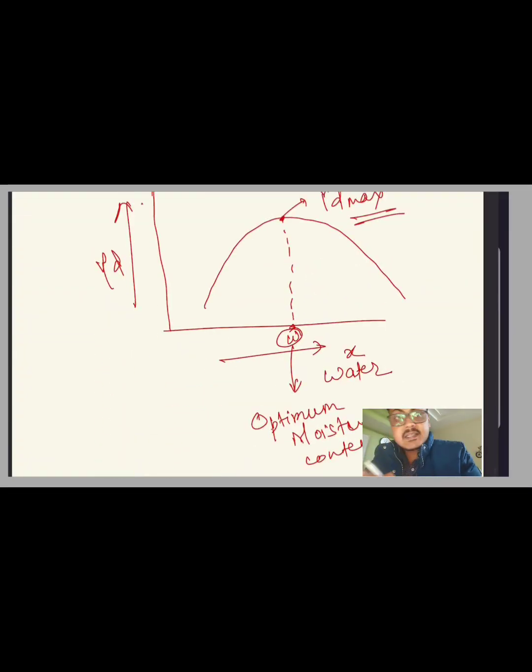What makes this graph important is that for the MDD, suppose we have some water content and some value of gamma D to the left of it, then the soil will be high in shear strength. High shear strength makes it favorable for use in road courses and embankments, where the need for shear strength is maximum.